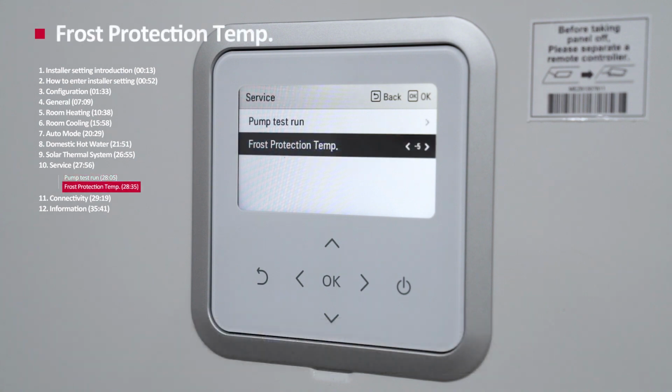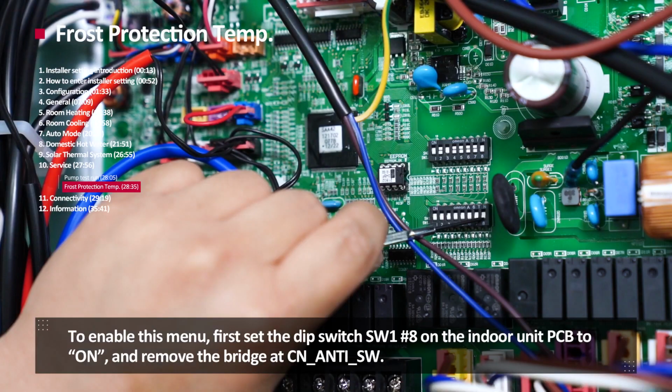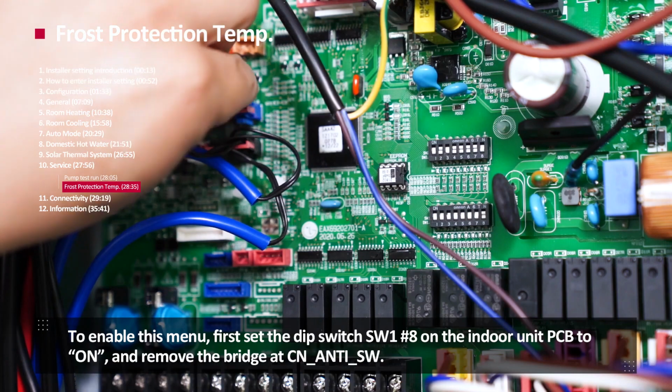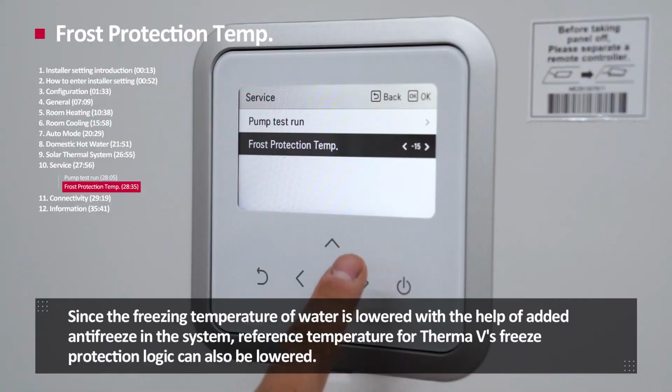Frost protection temperature. Frost protection temperature function is used to set the offset temperature for the freeze protection logic. To enable this menu, first, set the DIP switch software 1 number 8 on the indoor unit PCB to on, and remove the bridge at CN-ANTI-SW.